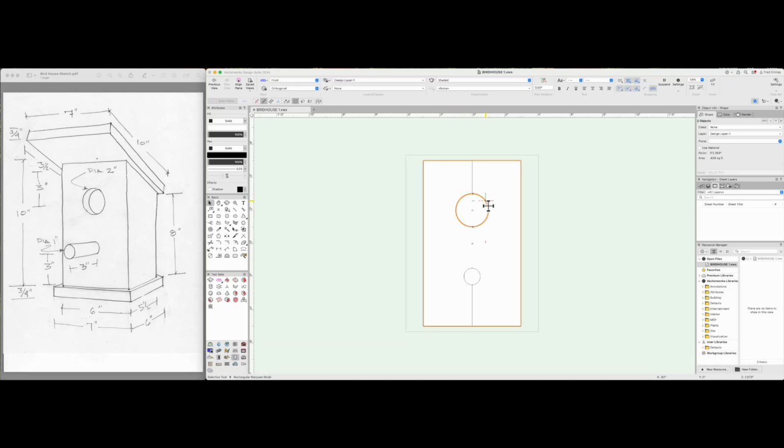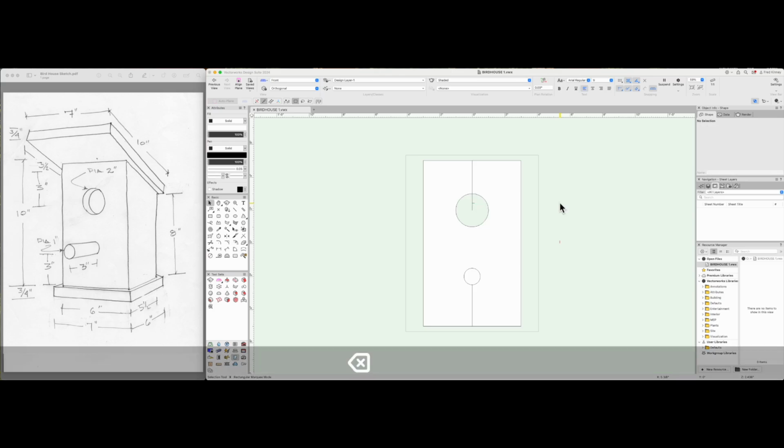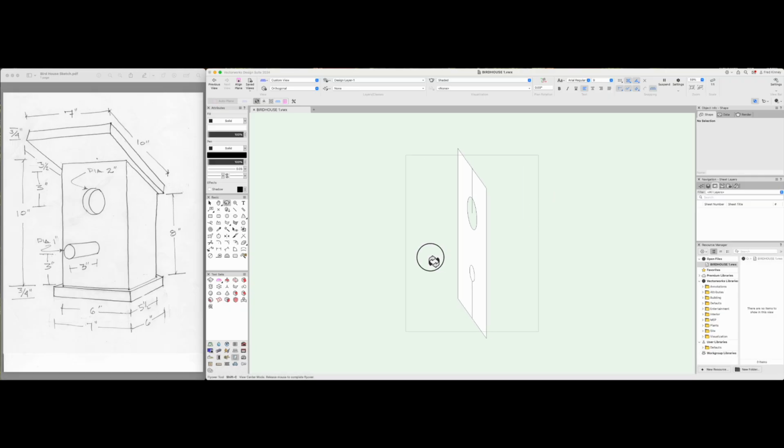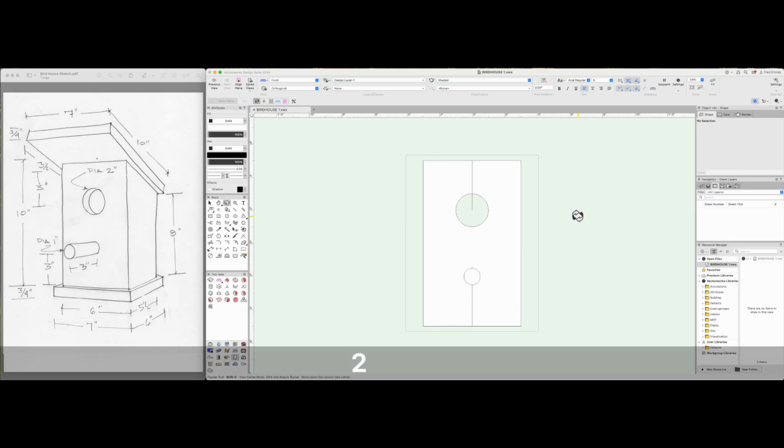When both of these are selected, right click. Come all the way down and see where it says clip surface. Clip the surface. It will know to clip the smaller thing inside of the larger object. Once that's done, those are actually 2 separate things. While it's highlighted, you can see with the orange around it, hit delete. That is now gone. You have a hole. Okay, again, it's still flat. See, it's still flat, but you do have a hole.